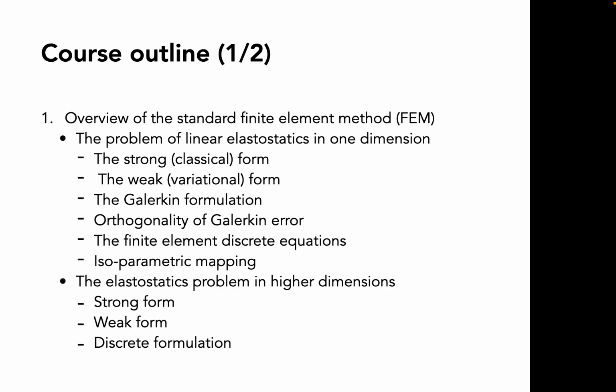And then, well, we all do this in an isoparametric setting. We're going to talk about what that means, superparametric, subparametric. The idea of isoparametric is basically that we approximate our geometry with the same shape functions as we approximate the field. So if we're solving for the displacement field, and that displacement field, let's say, is a quadratic polynomial interpolant, then if I approximate the geometry with a quadratic polynomial, that formulation in particular is called isoparametric, okay?